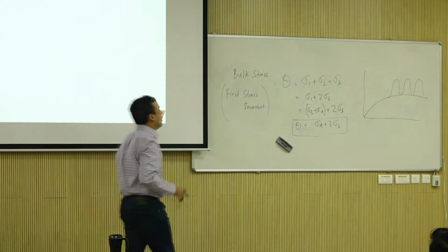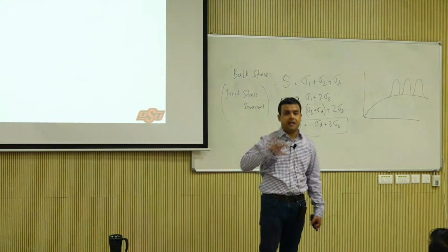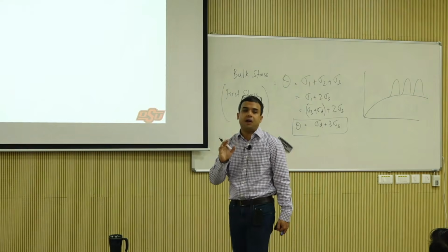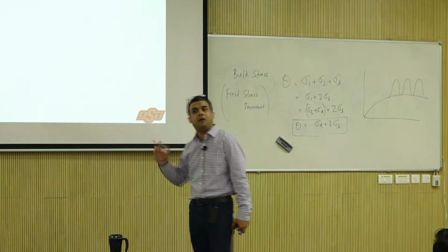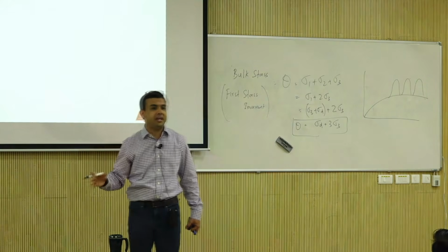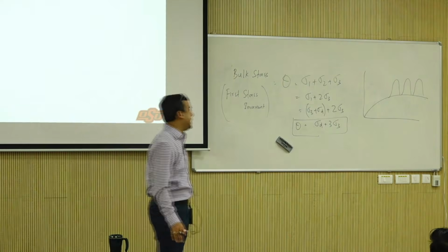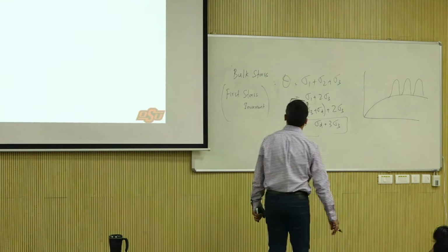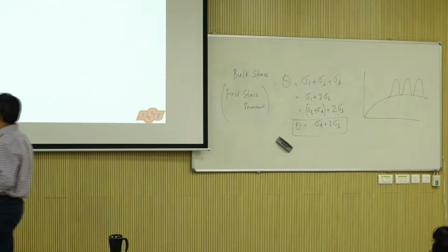The only difference is the permanent deformation test, which we will cover mostly tomorrow, will run a lot longer. Permanent deformation tests are done under 1,000,000 cycles, 10 million cycles, at least 10,000. The longest I have run for a paper was 10,000, not longer than that. And that gives you rutting.